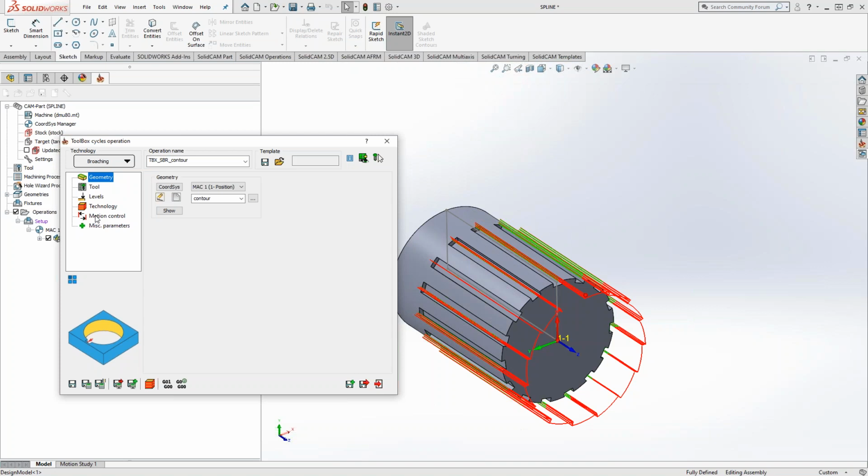So you could define your tool, and then you can use the manual turning toolpath to follow the exact trajectory of your tool. And in that case, you can get your arc out, you can get your kind of diagonal movement out. Every movement by the machine is controlled somehow either by a toolpath or by, let's say, an MCO. You can get that to output certain code just by hand typing it and plugging in. So there is a way to do what you're looking to do. It's just a level of complexity, either a post modification, an MCO, or some sort of combination of all the different things you can do in these toolpaths. There's always a way to do something.